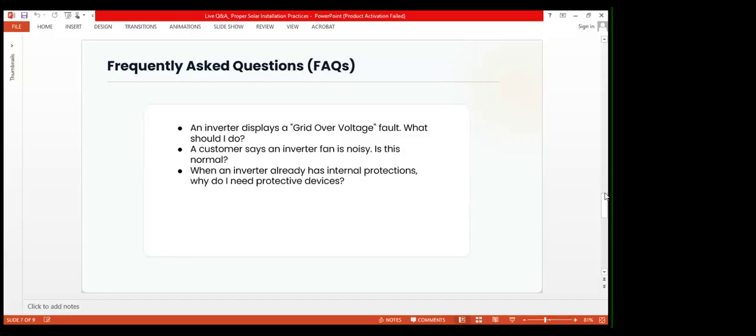Unless it's communicating and there is always power to charge the battery over a certain period, and you see that it doesn't go beyond that, and it's not taking current. Because one thing is for the battery to still be charging before it gets to 80%, and another is being at 80% while it's still taking current. If it's at 80%, still taking current and not going beyond 80%, then there is a problem with the battery. Because any battery that is taking current is bound to increase in terminal voltage, and the percentage will equally increase.